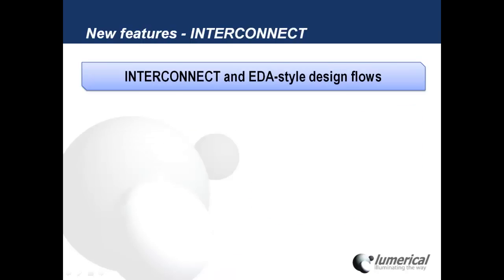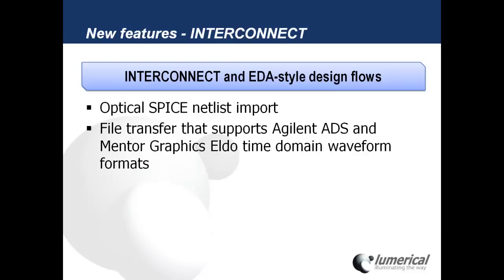For INTERCONNECT, we're looking towards an EDA-style design flow that can be used for photonic circuit simulation. And so we have optical SPICE netlist import as a feature, as well as a file transfer method that supports Agilent ADS and Mentor Graphics ELDO time domain waveform formats.